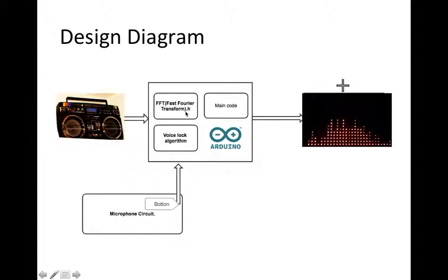We will then use these frequency magnitudes to light up each of the columns of an LED matrix. The magnitude of each bin of the Fourier transform corresponds to the number of LEDs in a column that it will light up, i.e., a larger magnitude will result in more LEDs being lit up. In this way, it will visually display information about the frequency spectrum.